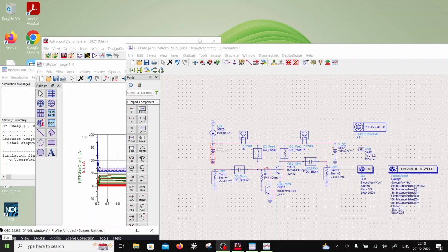You can run this simulation to learn more about BJTs, and when you design power amplifiers or low noise amplifiers, you will come to know how BJTs can be used for various applications. So in this course we are going to limit ourselves to only DC characteristics. Another thing is, in the class I'm going to explain the other RF characteristics, like what is FT, FT versus IC characteristics, and beta. Also we have one more experiment to plot log of collector current and base current versus VBE, which is basically called the Gummel plot. So first I'll explain in the class what a Gummel plot is, and in the next experiment we will plot the Gummel plot, and we will try to see if I can plot the FT IC characteristics. Okay, so I'm going to stop here for this experiment.